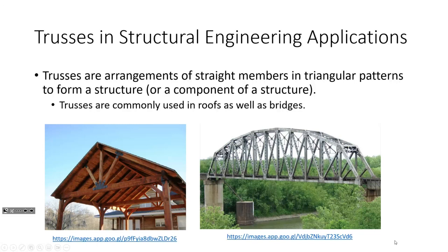They're expensive. Trusses take a lot of drilling, a lot of fabrication, a lot of potential welding, a lot of cutting. They are complicated. They take a long time to put together. They take a lot of man hours in the fab shop. So they are expensive. Okay, so you are only going to use trusses in areas where there's a clear benefit. I want you to understand as structural engineers when you would use them and when you wouldn't.